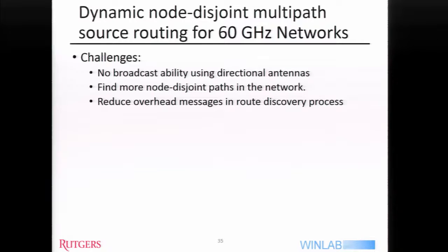It's pushed by the millimeter wave imaging at 90 gigahertz for airport radars, airport imaging devices. 70 because of vehicular-to-vehicular, but coming probably very soon to 28 as well. So we can talk, I don't know about hundreds, but in the more common sense of 18, 30 element, with each element having a few dB, so you build up significant gain with each array.